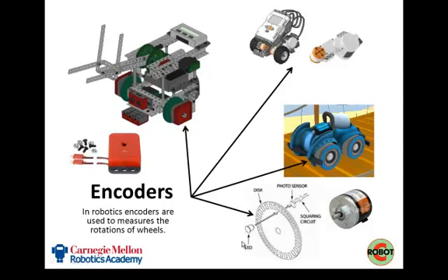And then you can see an example of an industrial encoder right here, where you've got an LED, a light emitting diode, you've got a phototransistor, and basically what happens is as that light goes through these little holes, it counts.